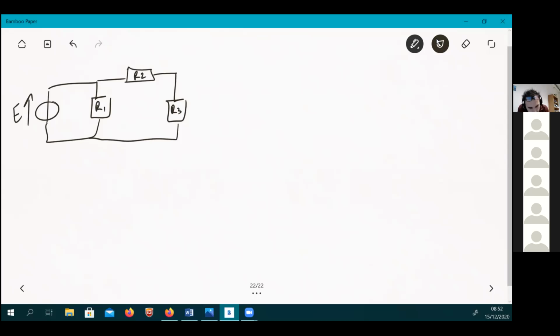The question is, what is the voltage UAB? So you have A here, you have B there, so UAB is only in this direction. Be careful because this is a common mistake you make in exams. We ask for UAB, so this is the only way of plotting UAB, always pointing towards the first letter.